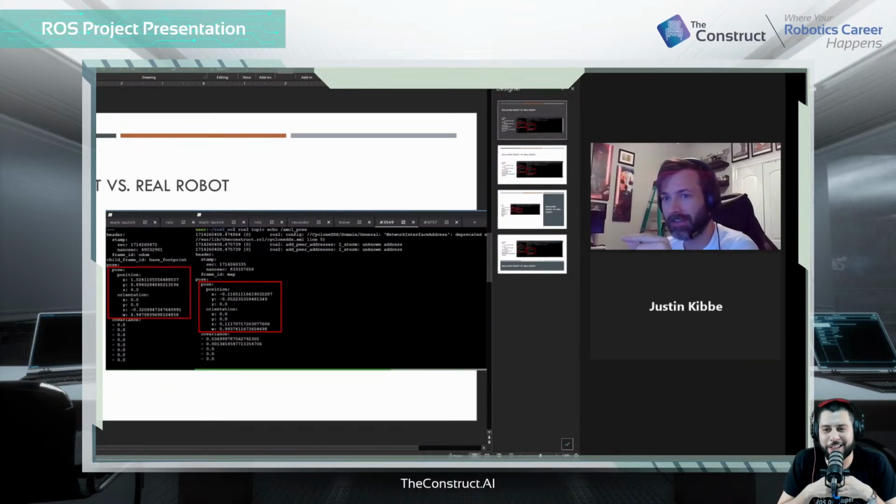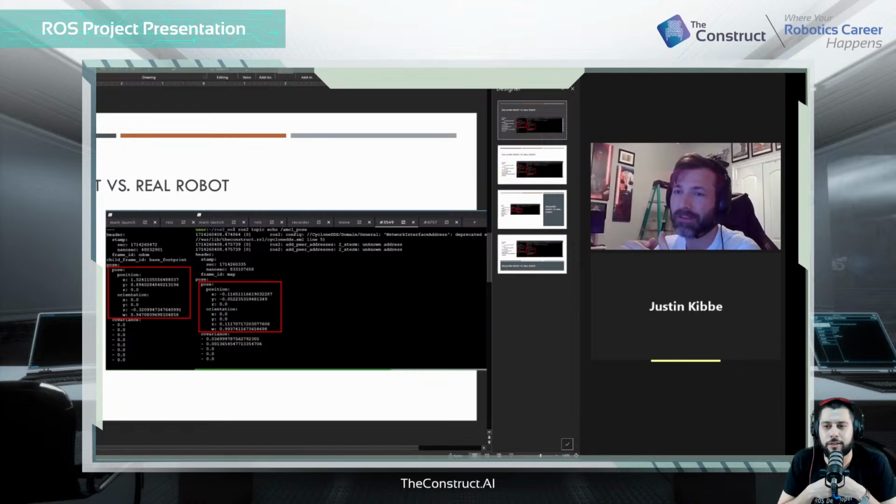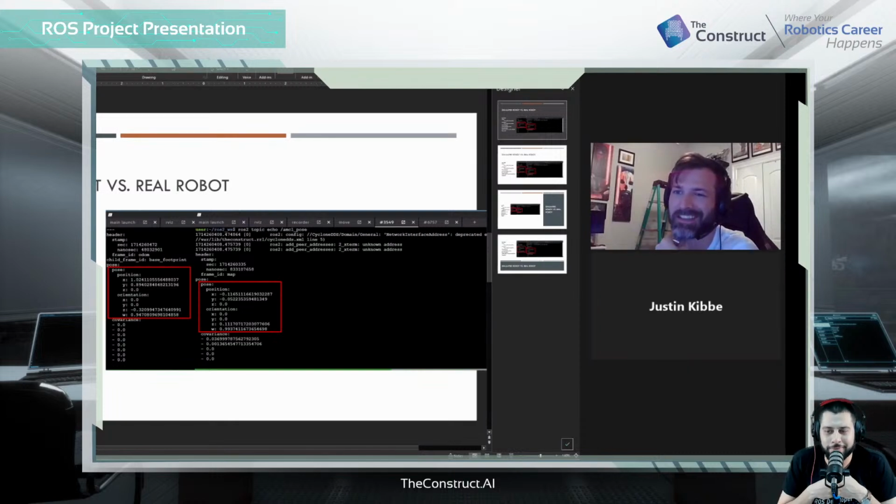Because you started mapping there, probably. Yeah, so whenever you start the simulation and you're doing the initial mapping, creating the map and all that stuff, your simulation starts at the pedestrian spot. Yes, yes. So 0,0 on AMCL pose and 0,0 on odom is the only one that's the same. That makes sense now. That's the reason.